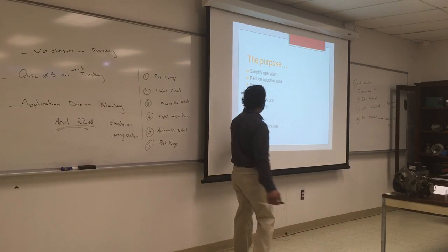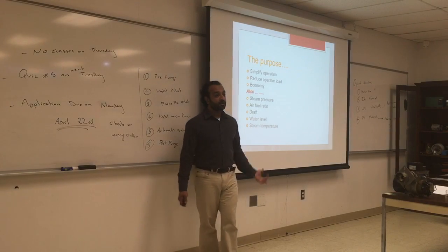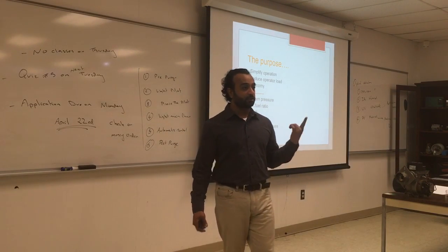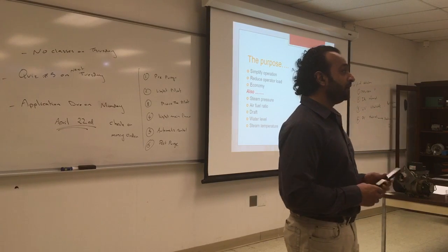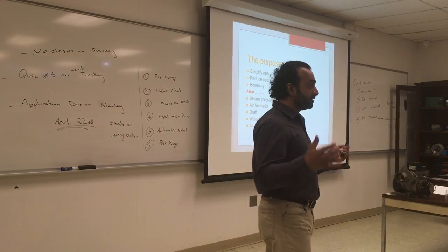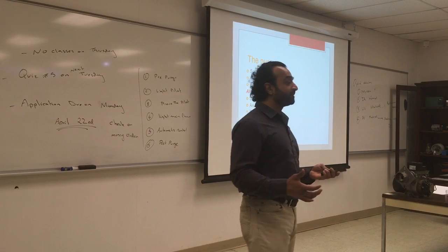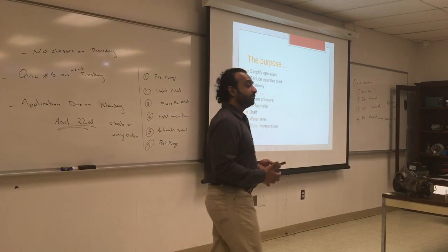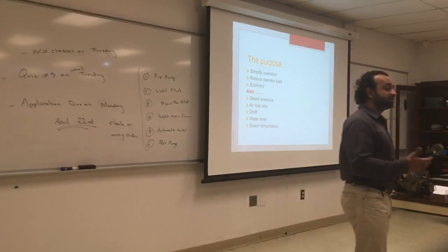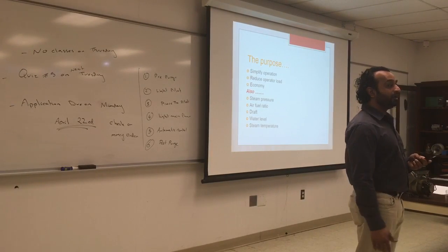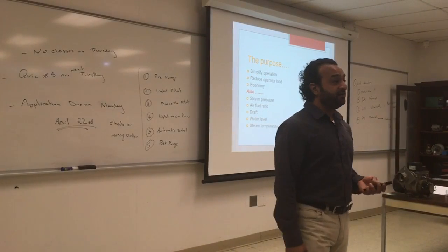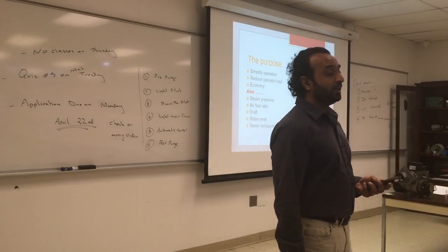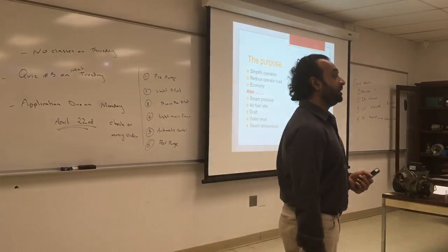So you want to control the steam temperature and pressure. As you increase the steam temperature, the pressure will increase, and as the pressure increases, there's a lot of force acting against the walls of the radiator and the pipes. If you exceed the limit without relieving some of the excess pressure, you might cause a burst in the pipe. Steam pressure is very, very dangerous and very important, and never underestimate the power of steam.